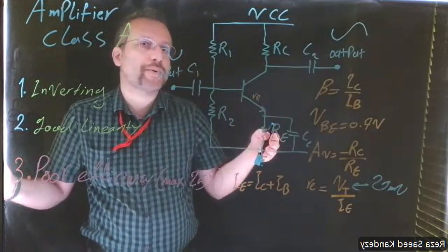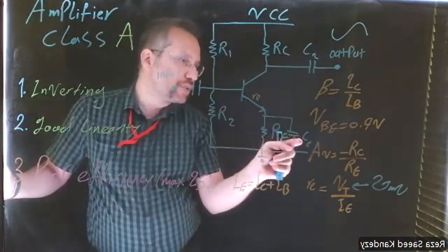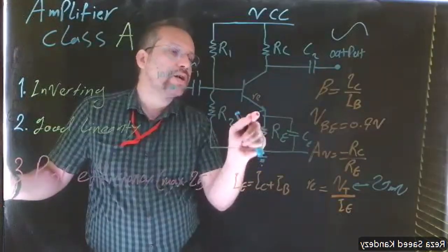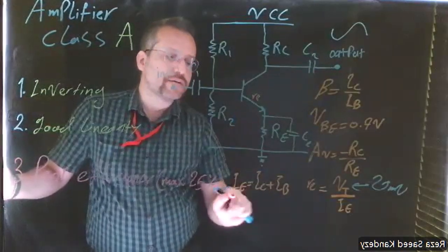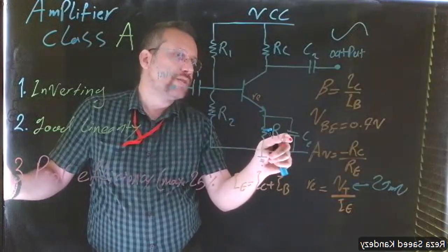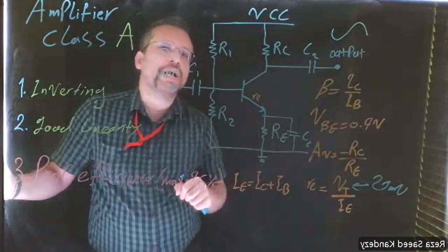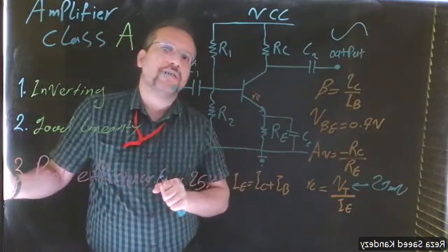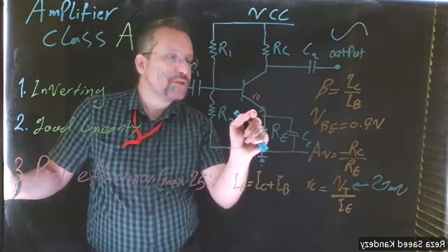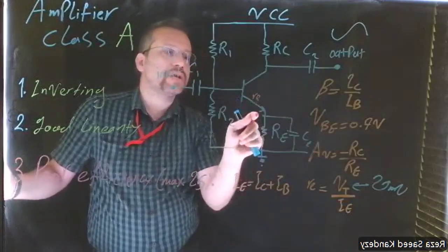So it would disrupt the whole design. What we do is use a bypass capacitor here to drain all the AC component in the emitter current. In AC mode it short circuits the AC, so the AC would not go through the RE. So we have a stable voltage at our emitter, which is only the DC component. It swallows all the AC part that gets to the emitter.